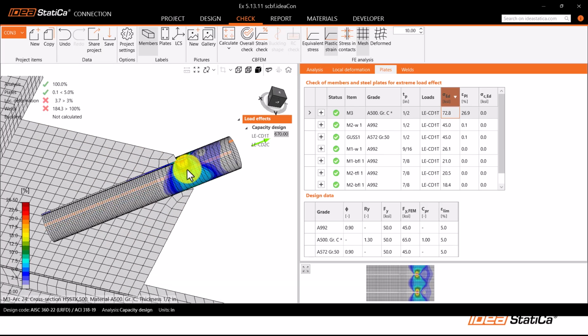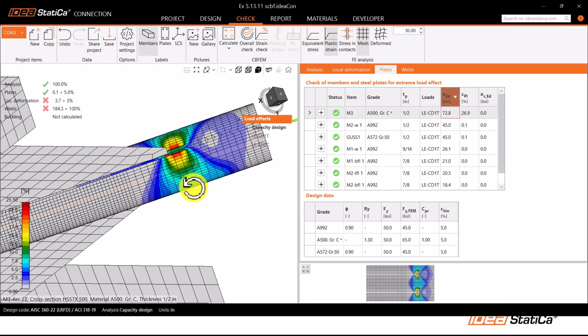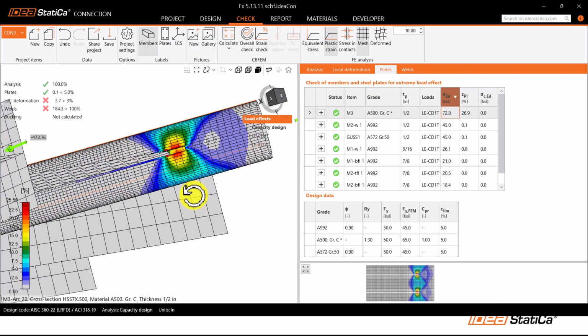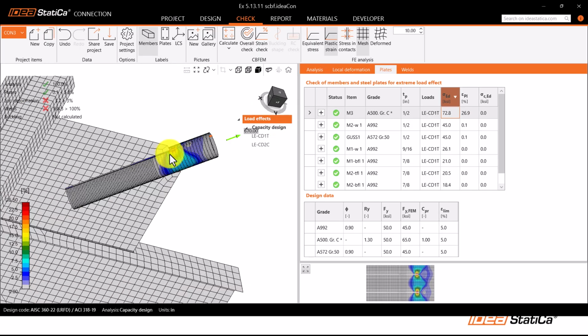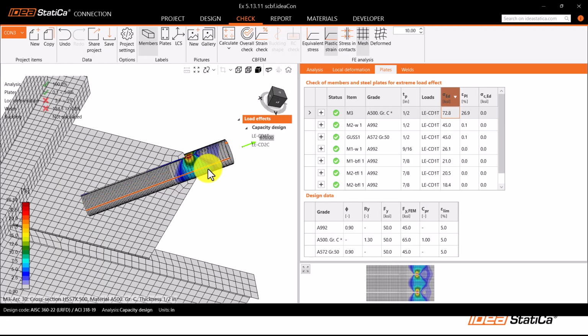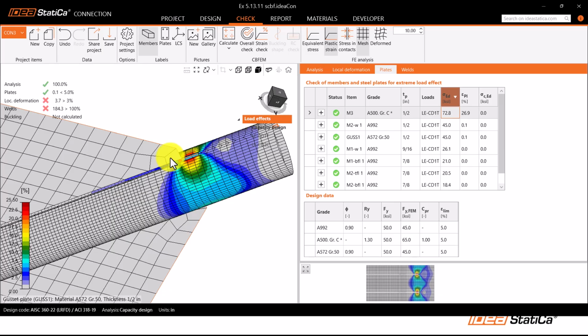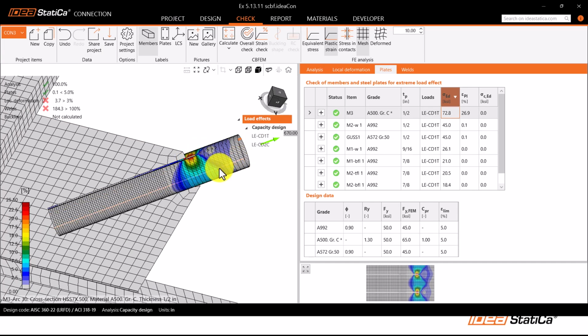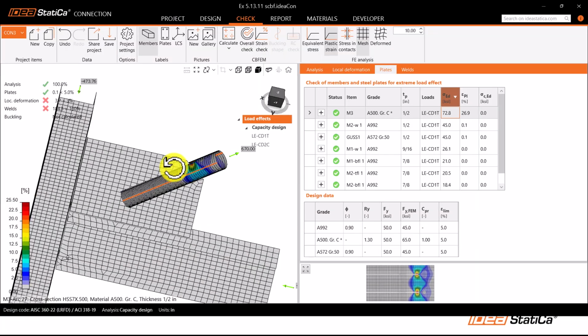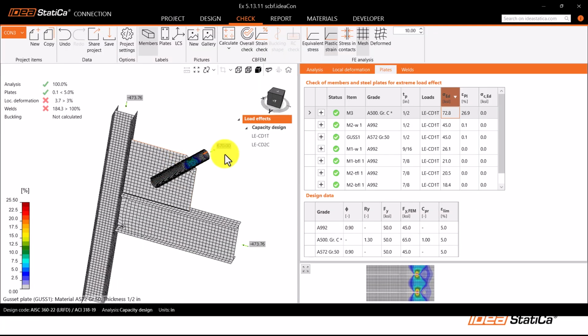So if you have gone through the example in the AISC Design Manual, in this example, they are adding a reinforcement here because this is reducing the area of that member, so we need to replace that area with a reinforcement on this HSS, right? So that is for the tension case.